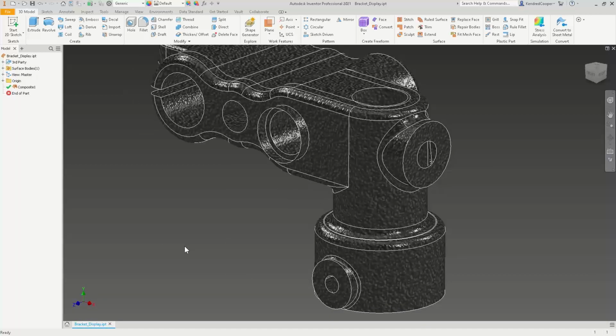So you've got to clean this up. Various ways to do it. You could use the traditional surface commands. One problem with using traditional surface commands is they create a history item in the tree. Now it can be a plus, it can be a minus. It can also clutter your tree with a lot of steps that you don't need. Now, if you need to go back and undo or tweak something, that can be a benefit. You've got it right there in the tree, go back, edit that feature, make an adjustment, you're good.